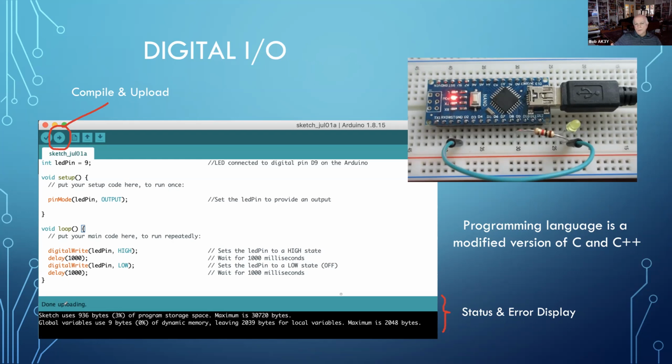Okay, so this is the very simplest part of the Arduino. It allows me, through all these digital interfaces, D0 through D13, I can use those for logic highs, logic lows. Gives me lots of things I can program to control different functions. I want to control a TR switch. I want to control a relay that's connected to a filter that's used for sideband on 40 meters, and then I want to connect it to another one that's connected to 80 meters. That could all be done through these digital interface pins. And if you look at the bit 40, which was the Indian QRP rig, you'll see that the Arduino is used for exactly those purposes as well.